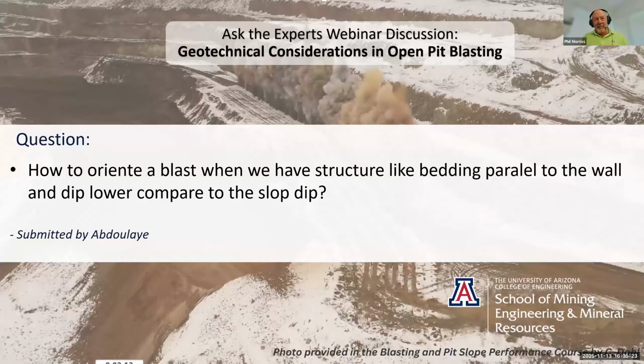With repetitive blasting adjacent to a slope, your cohesion is down, and at something up around 40 degrees, you're going to be lucky if you've got bedding dipping out of the face above that sort of an angle, and not have a slope that's going to end up basically sub-parallel to your bedding structure.